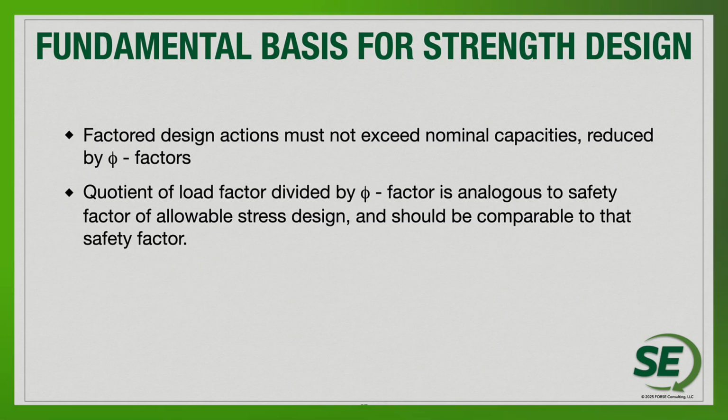So factored designs must not exceed nominal capacities reduced by phi factors. Again, the quotient of the load factors divided by phi factors is analogous to the safety factor of allowable stress design, and should be comparable to that safety factor. So again, just looking at the two and the differences between the two, what we would utilize for considering strength design.